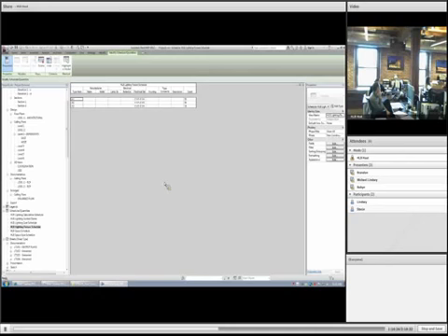I'd say have too many, and then you can always remove them. If the idea is that we are going to export out to Excel anyway, because it just ultimately will look better for formatting, the formatting controls probably won't be satisfactory within Revit. And you can't hide columns if there's not data that we want. You actually can. Right. You can hide them. So the count, for instance, if the contractor's going to be looking at it, we don't want them to see a count, we can hide it. Okay. Yeah, we can hide it here.